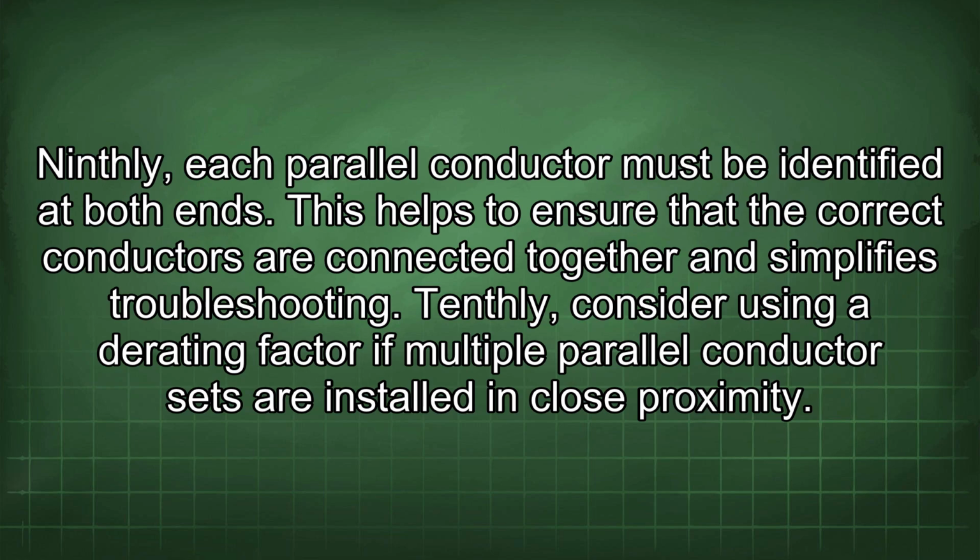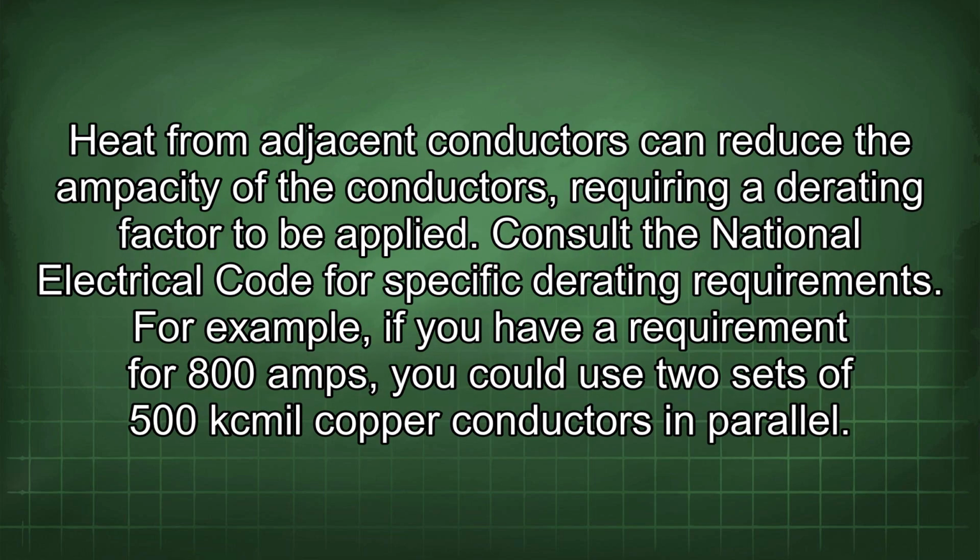Tenthly, consider using a derating factor if multiple parallel conductor sets are installed in close proximity. Heat from adjacent conductors can reduce the ampacity of the conductors, requiring a derating factor to be applied. Consult the National Electrical Code for specific derating requirements.